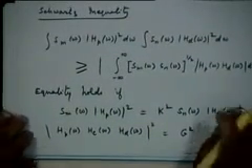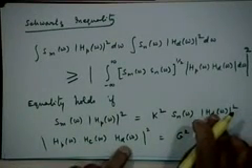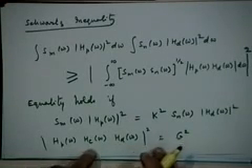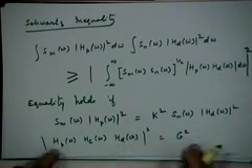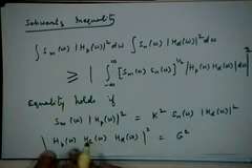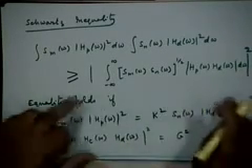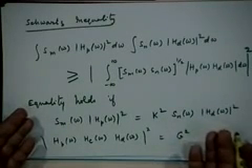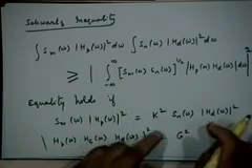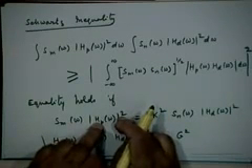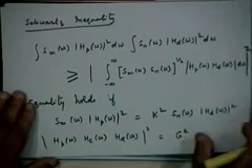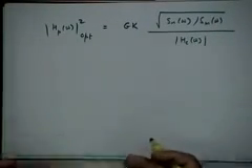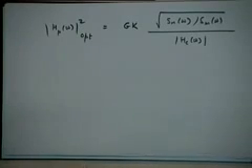Basically, using these two equations, I am eliminating Hd(ω) and solving for Hp(ω). That is very easy, because you substitute for |Hd(ω)| square from here. You will get this entire expression in terms of |Hp(ω)| square, which you can then solve for Hp(ω). Actually, Hp(ω) will come in the denominator to the power 4, and then you take the square root of that, and that is why you finally get this expression. I have skipped one or two very simple algebraic steps.